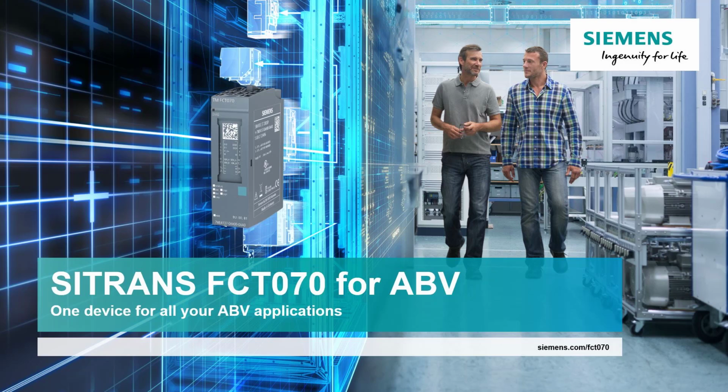Today we're going to take a look at the FCT070 transmitter for Siemens Coriolis meters. This transmitter sits in an ET200SP HF I/O card or on an ET200SP CPU, and it is capable of storing 17 ABV curves for all of your applications within the distilling industry.